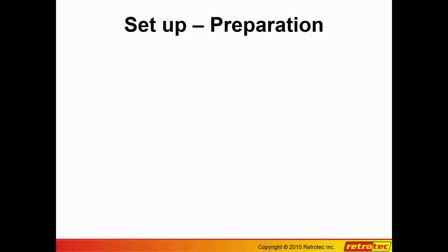So in terms of the building, we're going to be sealing off all of these openings, and there are a number of techniques that can be used in doing that. I won't get into it, but suffice it to say that when you're getting down to the tightness level that's required for these, at 0.6 air changes per hour at 50 pascals, even minute little pinholes, not quite pinholes, but say nail holes, can actually make a difference.